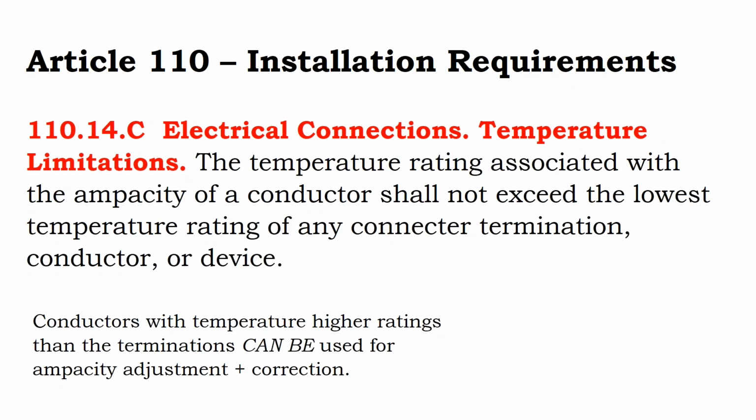The issue is if you have a disconnect switch where you have an electrical connection coming onto that disconnect switch, and that disconnect switch only has a 75C rating, and you've been using solar cable and solar equipment that's rated for 90C, you may find that you have to redo your temperature calculations for a 75C rating. In particular, you have to do a 75C calculation for that terminal in that box simply because it doesn't have a 90C listing. And so you need to go through all of your equipment. It might be that 75C is sufficient, and it usually is sufficient,